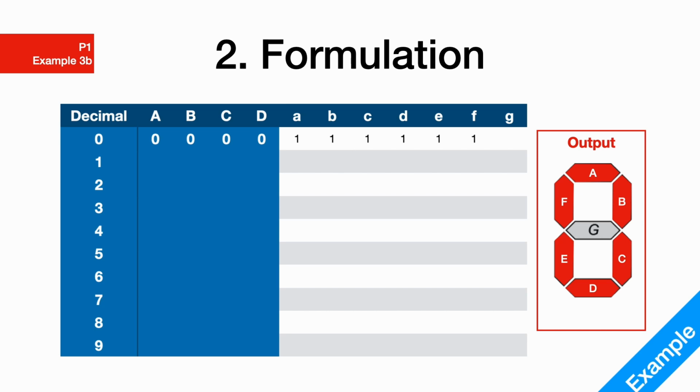should be the appropriate arrangement, so that A, B, C, D, E, F, only these parts of the LED are lit up. So the lowercase a, b, c, d, e, f are lit up and outputting a positive signal. And G in this case would not be lit up, so it would receive a 0 value. For the sake of simplicity, if we don't write down the actual number in the truth table, it is considered 0. We proceed to number 1.